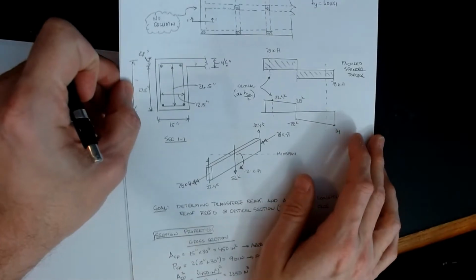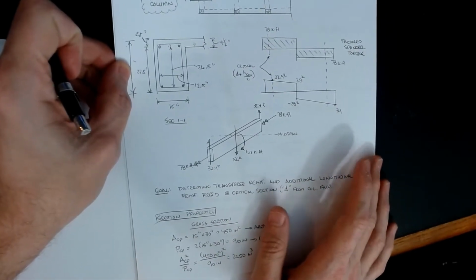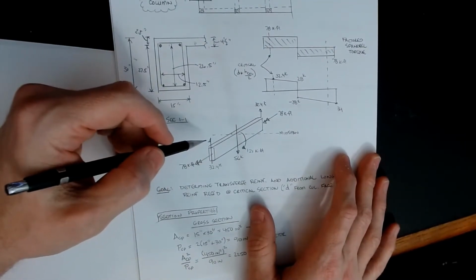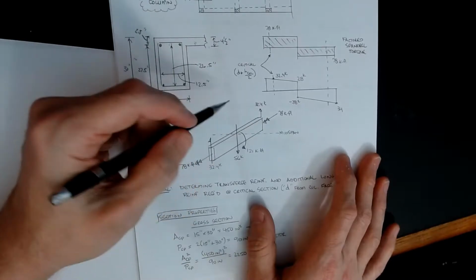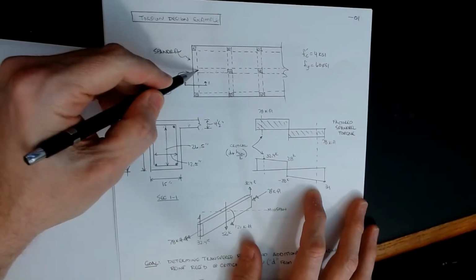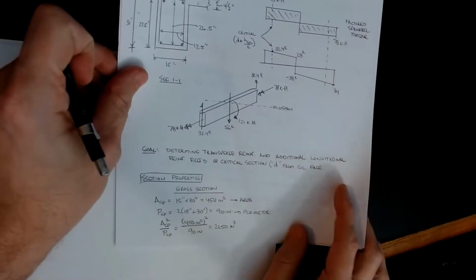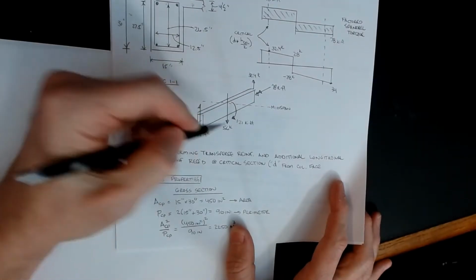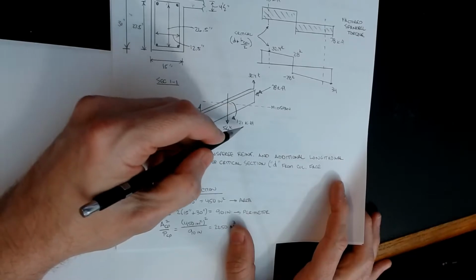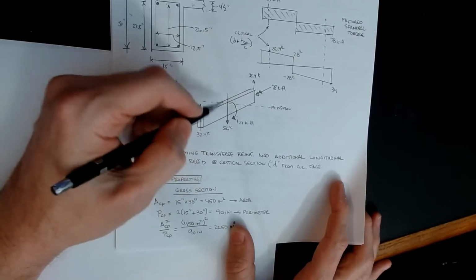Okay, the next piece that we have is now the loading diagrams. What I've done is I've drawn what's happening on that spandrel beam up in that plan view. So here's my beam. The girder that's coming across the middle here is putting a vertical shear into the beam, and it's also introducing a moment into it, and it looks something like what you're seeing here. So the vertical shear is 56 kips, that's the end reaction, and it's putting a moment of 121 kip-feet into this beam. This is the guy that's causing the torque, in addition to this one.